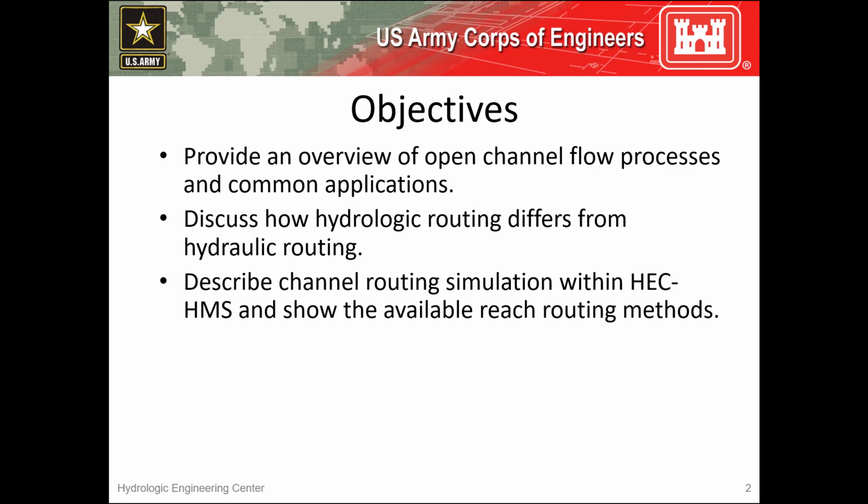Just a heads up, we will spend a bit of time looking at equations in the beginning, but it's important to look at the equations to understand how hydrologic routing differs from hydraulic routing. Afterwards, we'll talk about the various ways in which reach routing can be simulated within HEC-HMS.